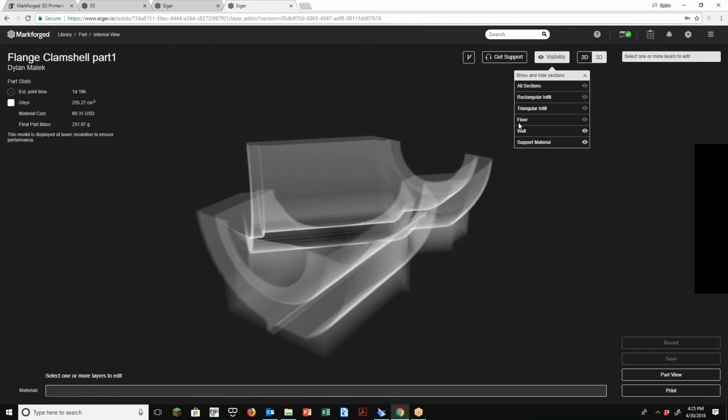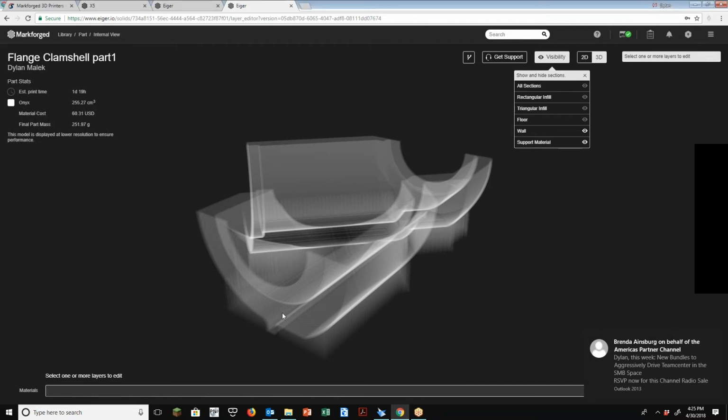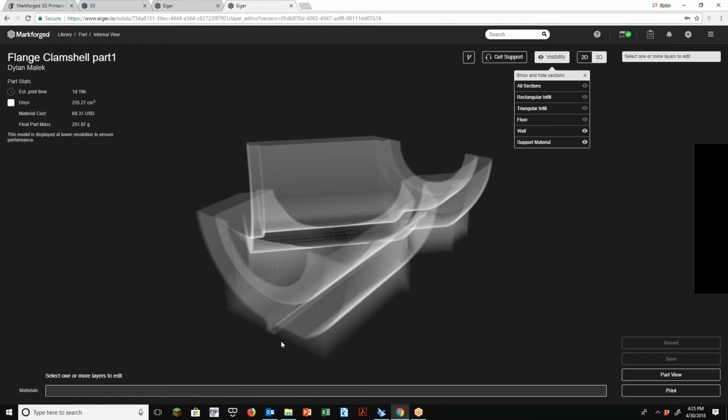The floor is what's represented at the very bottom of the geometry. Typically if you're running carbon fiber and you tell the software to do it, it will add carbon fiber at the very first 3 or 4 layers into the floor, and the same thing at the top of the part. It automatically does that for you. So there's the floor area, top and bottom, and that's where it will put the supports above, depending on what type of fill you use.